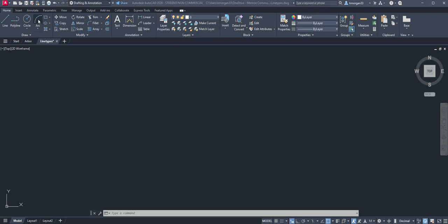Alright, we will go to the Home tab and then go to Properties. Of course you have line type, you have by layer, you have this little icon. When you look at it carefully, line type is here, showing you different line types, and this is line weight.